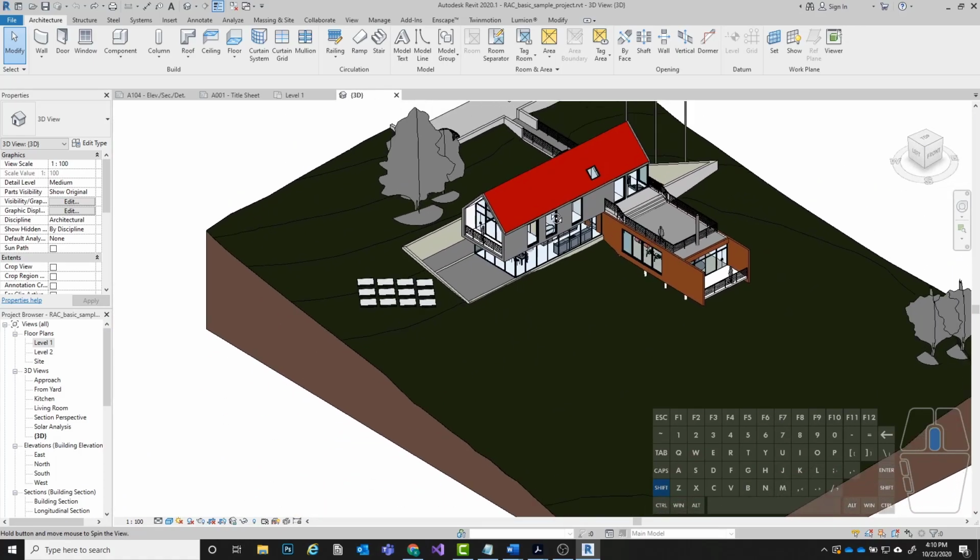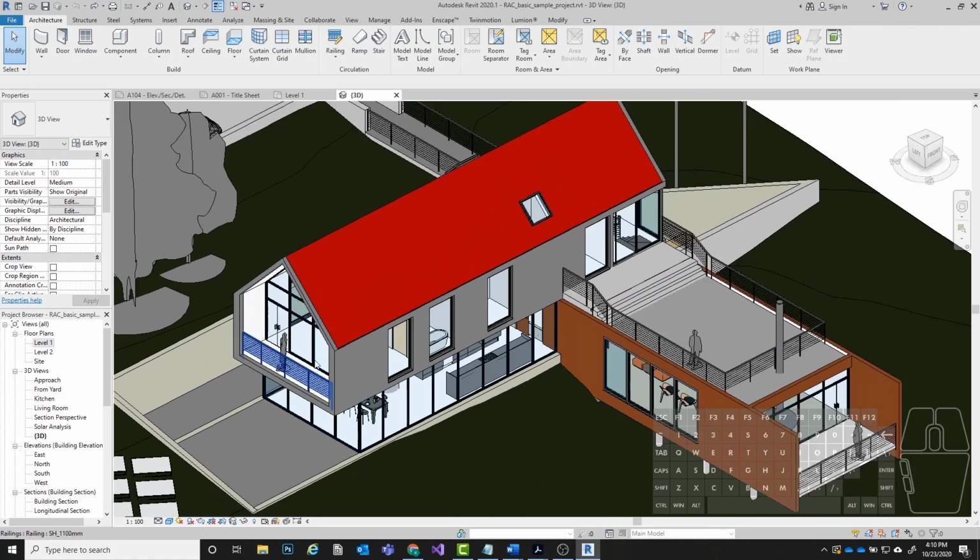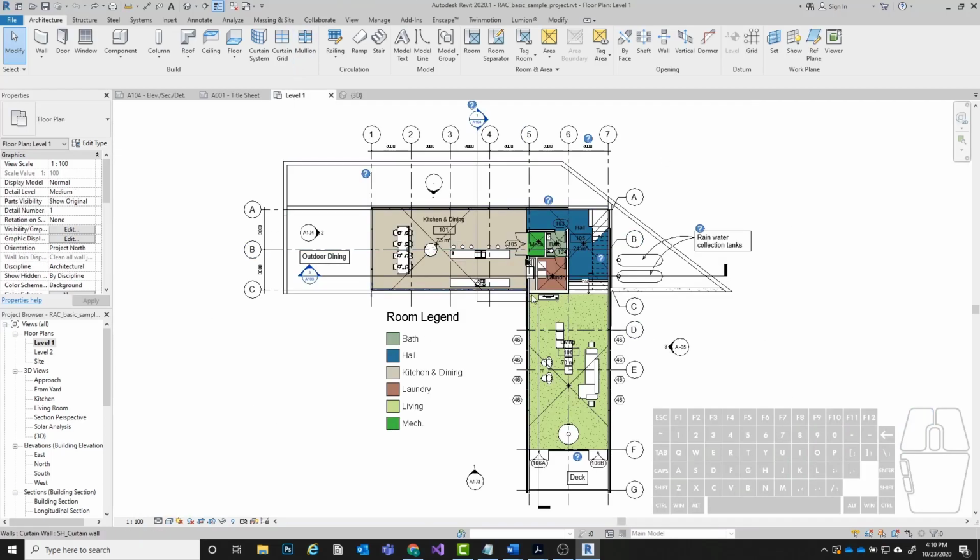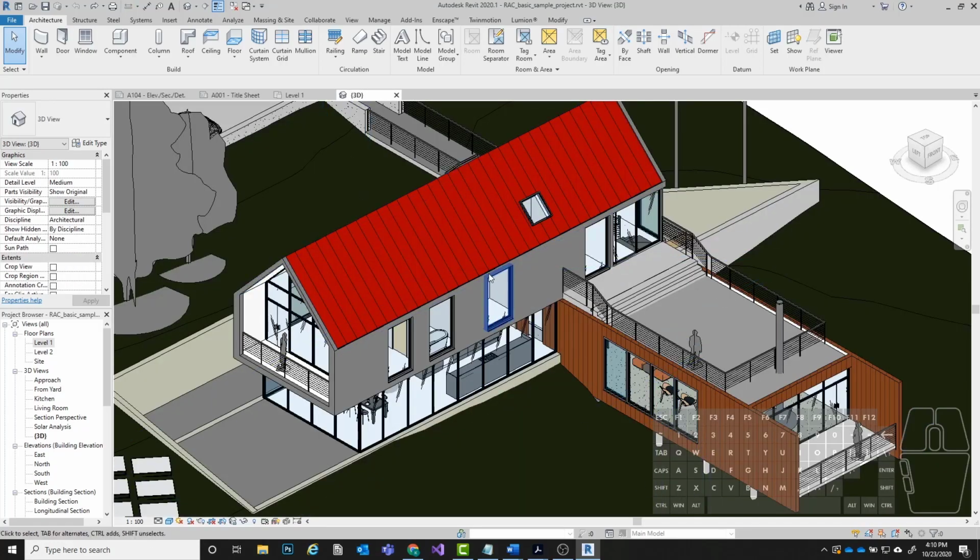So this is my default 3D view. But as we're creating things inside of Revit, and you'll see this as we go through and start working in the labs, we're going to be drawing these elements, all these 3D things, as we would inside of AutoCAD. We'll be working on a floor plan view, just a top-down 2D view, like we were here on level 1. This is going to be our normal, typical working view. And as we draw, very similar to AutoCAD, they will automatically be appearing in 3D in the background. And we can always toggle to a three-dimensional view to see how things are looking in 3 dimensions.